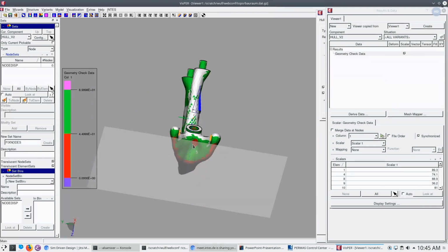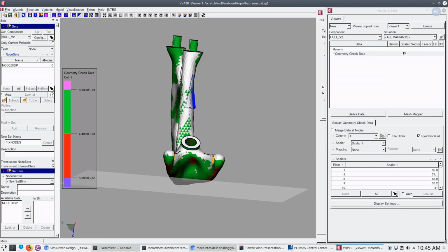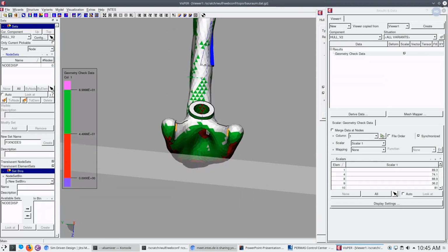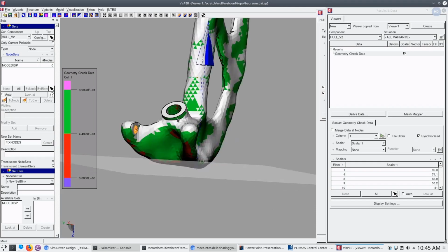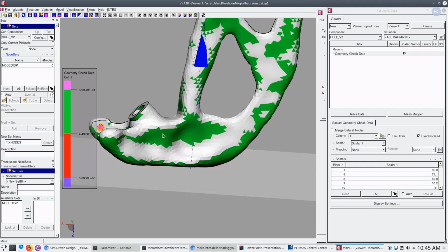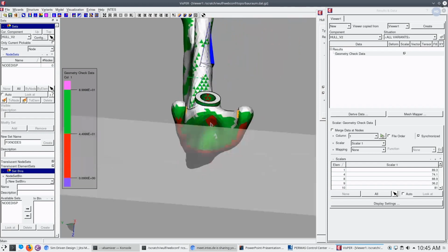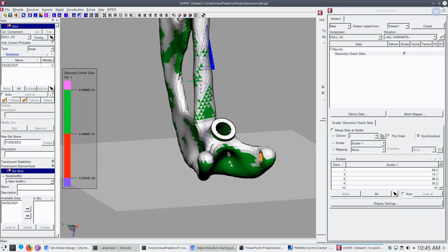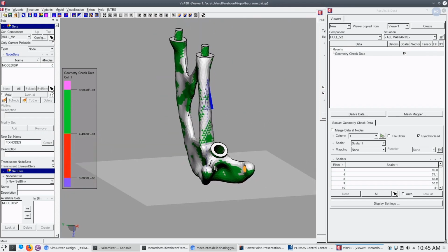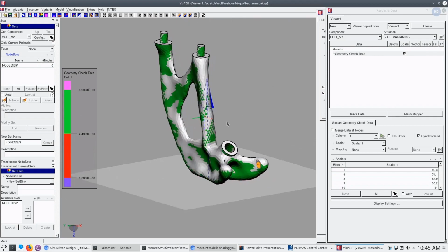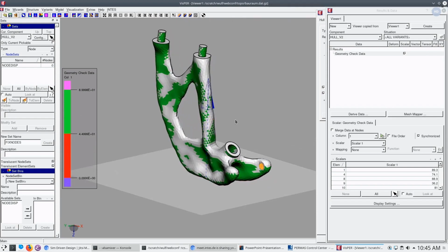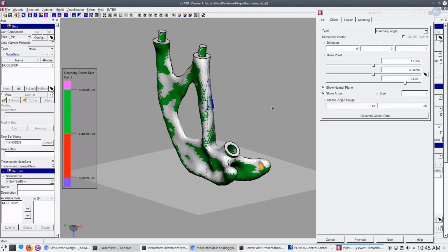And here some violations still left, because you remember we accepted some tolerance of support structures, but much less than before, and especially these small holes where it's maybe a tedious act to remove the support structures from these small holes. They are closed in a physical useful manner. This is what the topology optimization actually does. So now we have a design that is, with regard to the need of support structure, maybe a more useful design. Okay, I close.